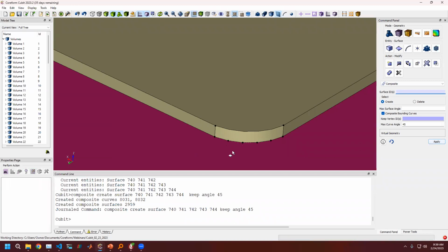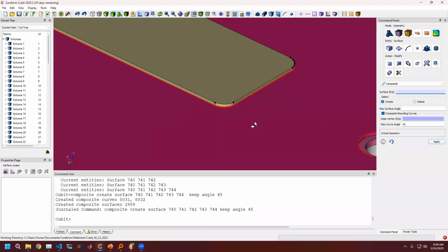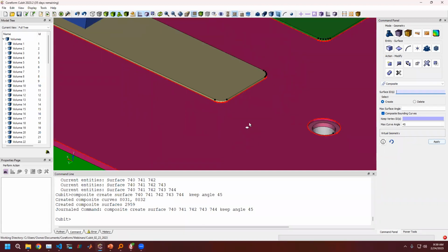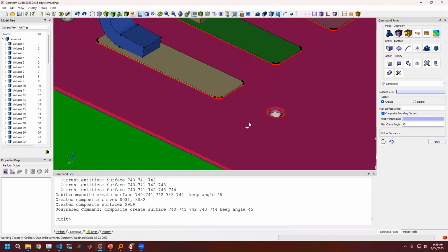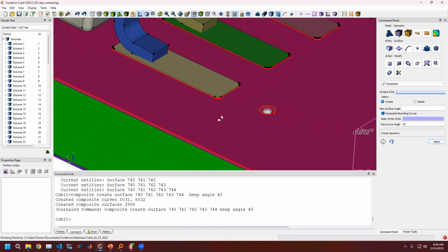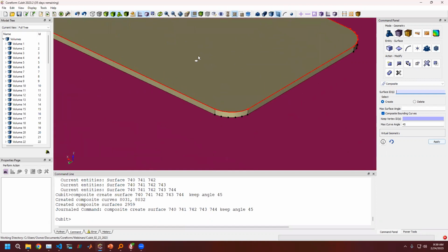And there's a volume below it, which is why we're seeing these vertices from the volume below. That's one way to clean up, but that's again happening on virtual topology, which is a step you want to do as a last resort, maybe right before you're about to mesh. But if we want to do CAD operations,